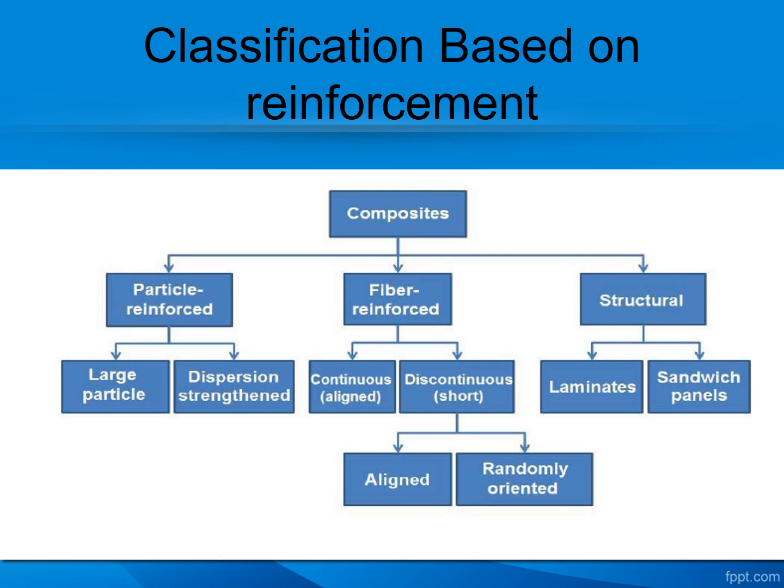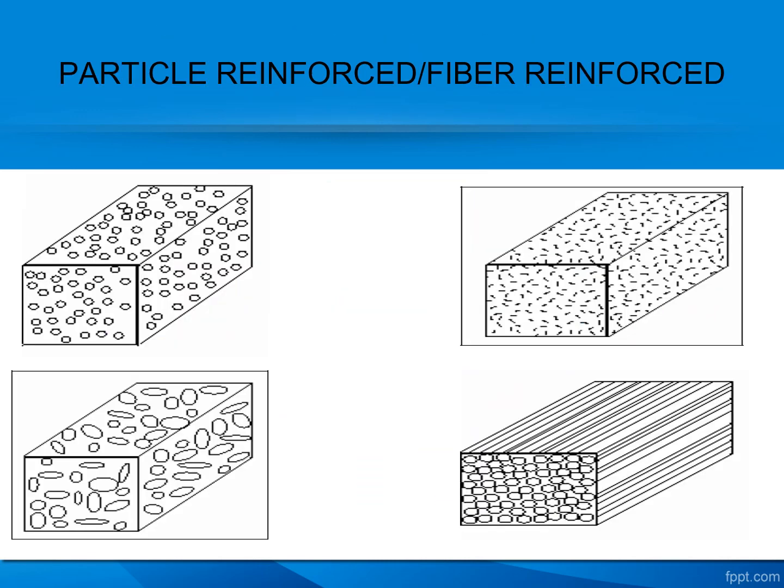Classification based on the reinforcement. Composites are generally classified in terms of reinforcement: particle reinforced composites, fiber reinforced composites, and structural reinforced composites. The fiber reinforced composites are again subdivided into continuous and discontinuous fiber reinforced composites.